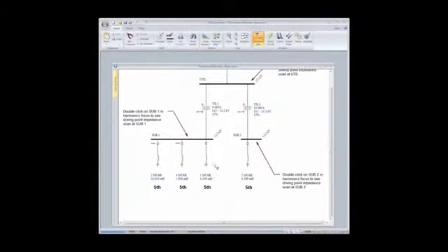And I will just have to admit here on the inside of EasyPower, this filter wasn't necessarily put in here for designing. It was predominantly put in here just to simulate it. But if you're doing harmonic filter design, you actually want to see the actual voltage and conditions on this capacitor itself. And in that case, you may want to break it out.